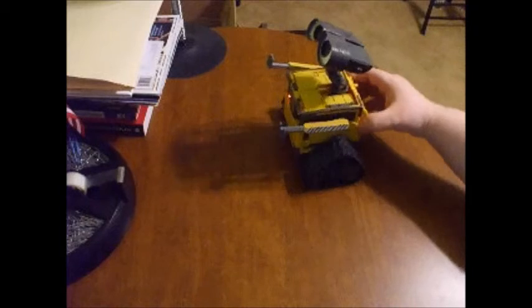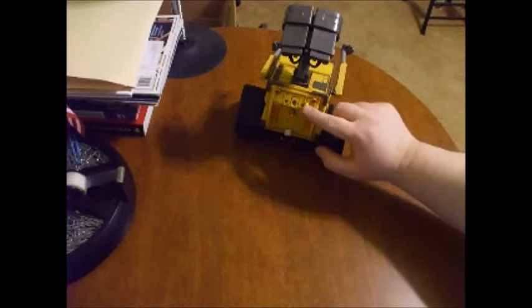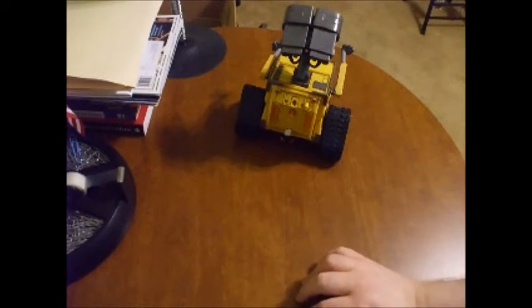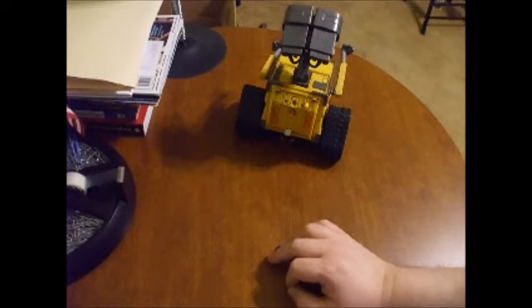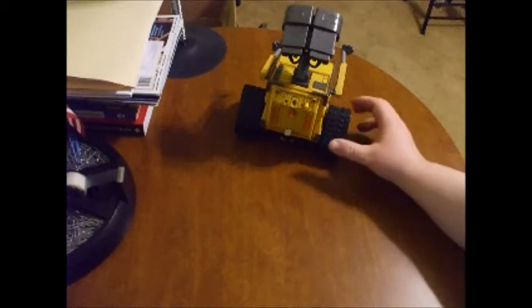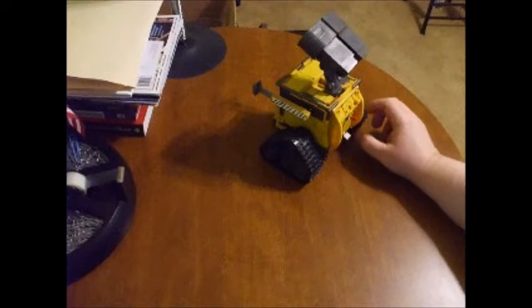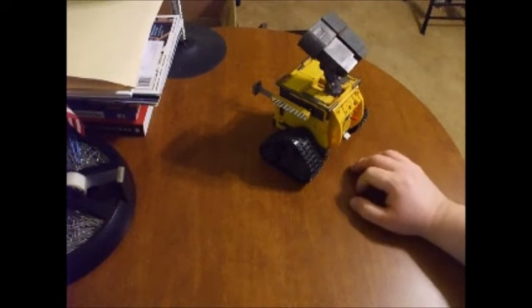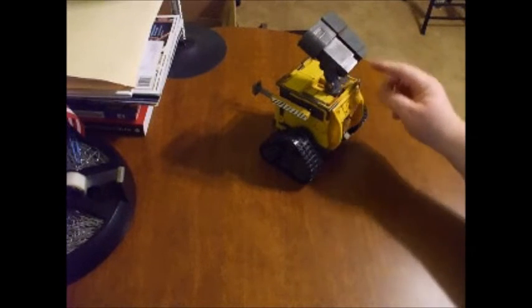And then this model WallE had a button here, and I've got this button and this touch button here hooked up. They're both interconnected to the ADC, one of those ports, through a set of resistors to give different values between which button you press, either this one or this one.